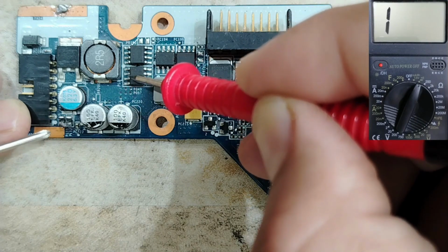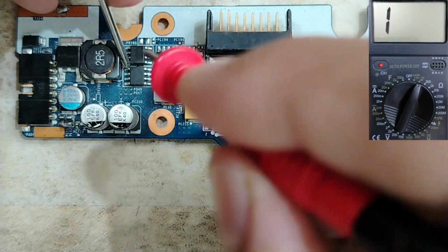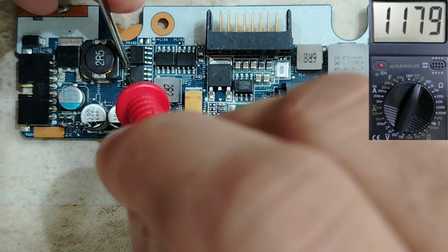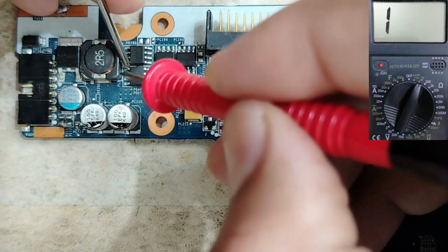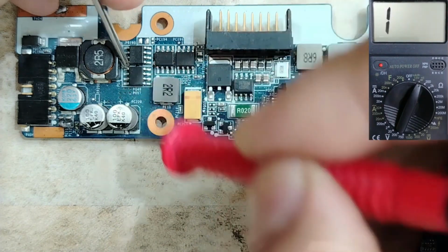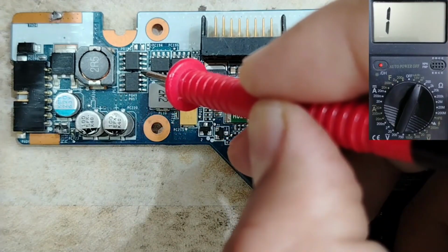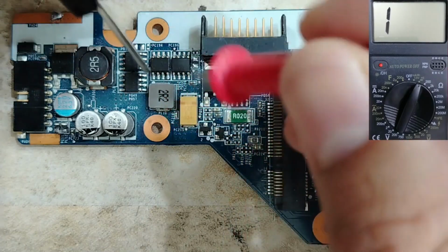So 3 pins are for the source. If we check these 3 pins, you're going to find continuity. Do you see? The first pin and the second and the third. We have continuity between these 3 pins. And this one is the gate, the 4th pin, and the other pins here are for the drain.